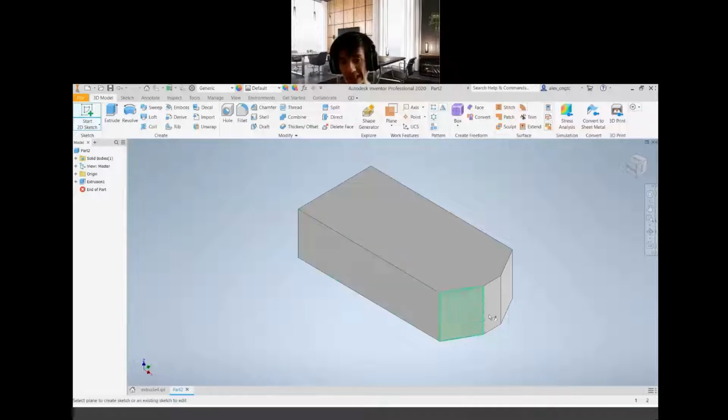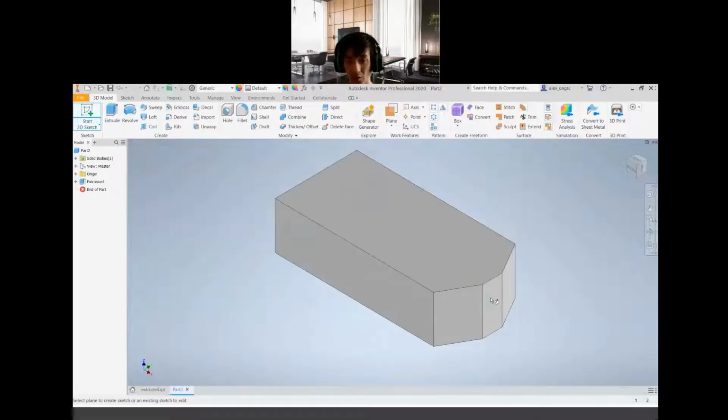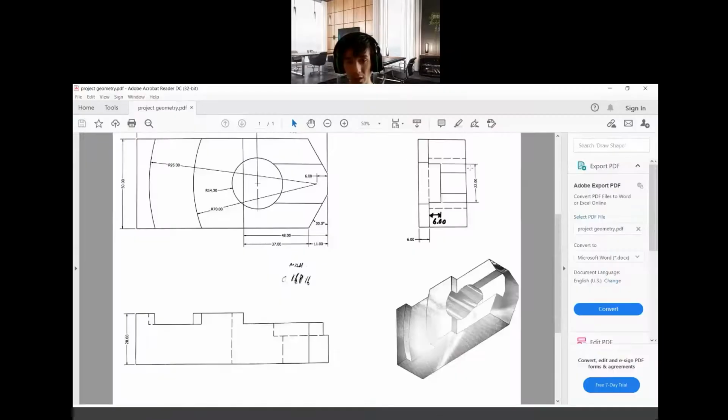Click on the surface that you create your sketching. So next one will be here. Please ensure that you select the right surface to become the work plane. Work plane is where you create your sketching. So for these features here, these two rectangles, we are going to extrude cut later. So we are going to draw on this surface here. This surface is in 3D.